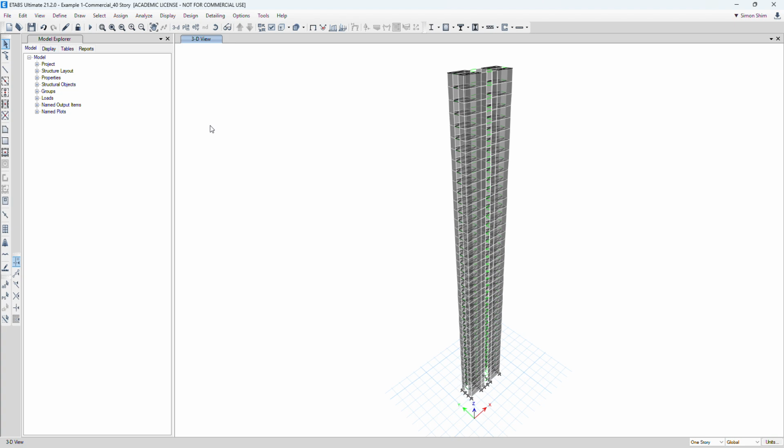Let me see, select the entire concrete wall and concrete link beam, because you don't want to select the steel beams and columns. And right click and select only member. Yeah, show selected object only. And put it in 3D, let's see.